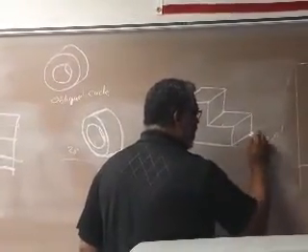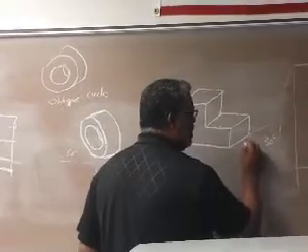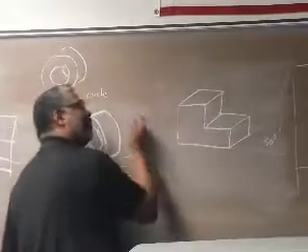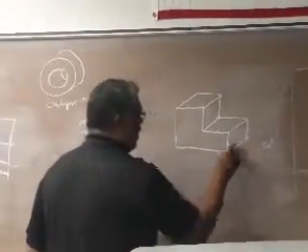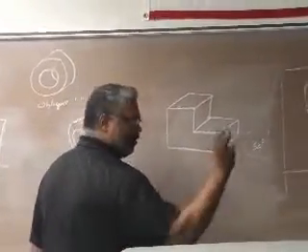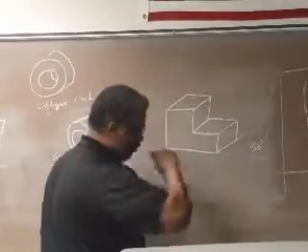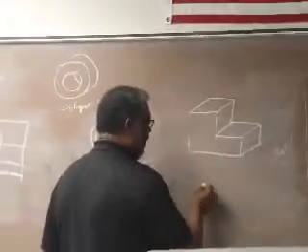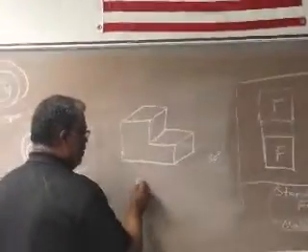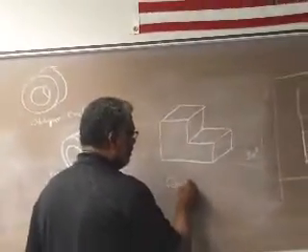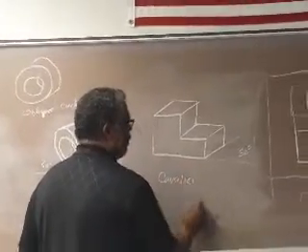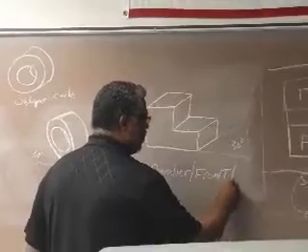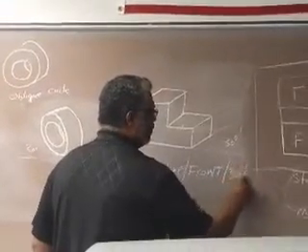Our receding lines went back at 30 degrees, and we drew them to the right versus the left. Sometimes you'll see a drawing, or in the textbooks it'll say draw an oblique. So your oblique might be a cavalier, front, 30 degrees, right.